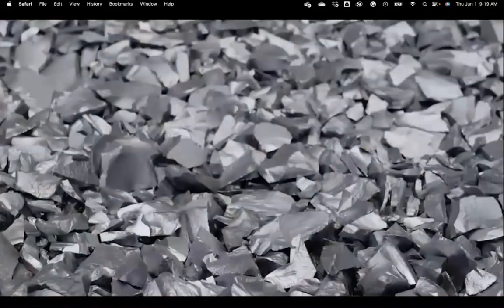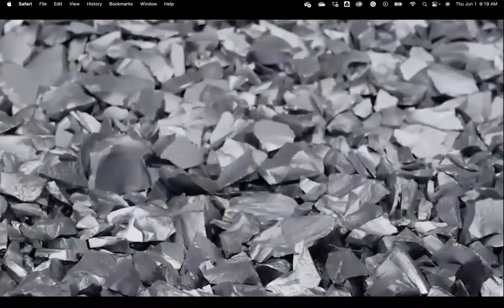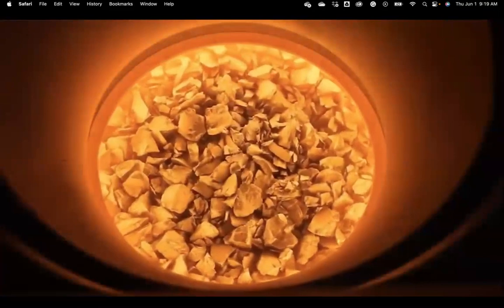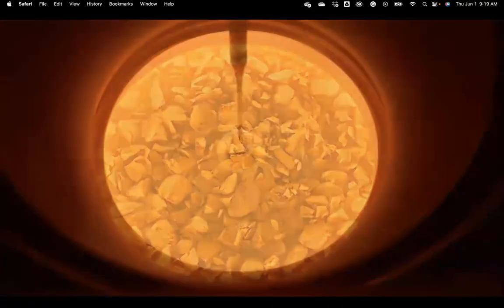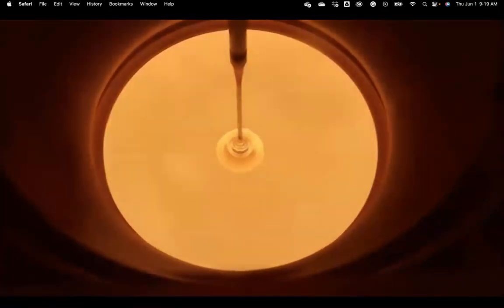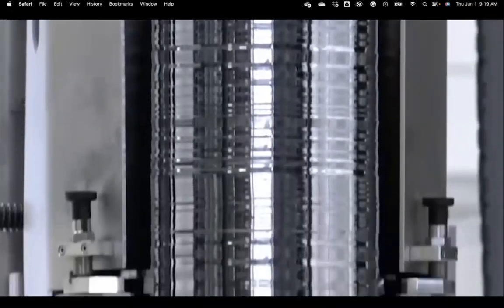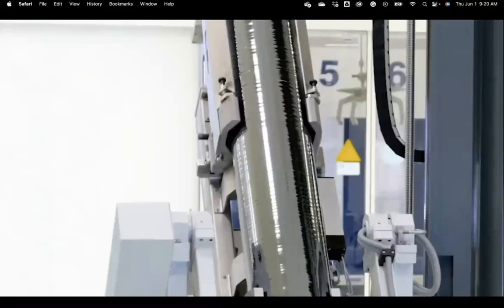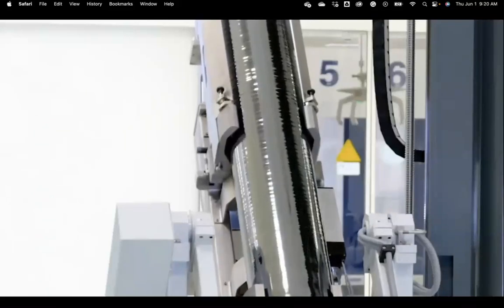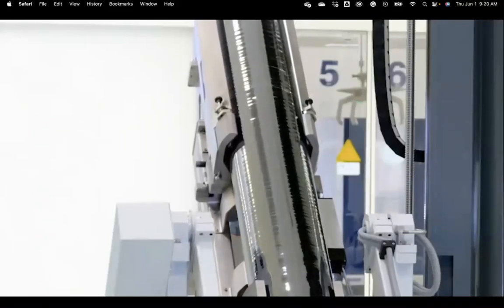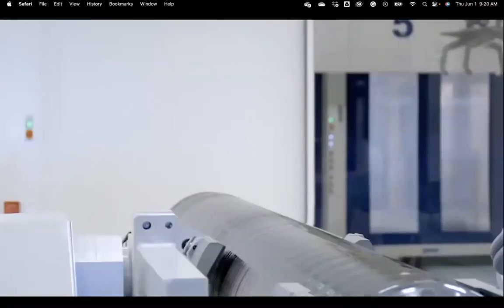To convert silica sand to silicon, the sand is combined with carbon and heated to an extremely high temperature to remove the oxygen. A number of other steps are required to create the finished product, namely an extremely pure monocrystalline silicon ingot called a boule, with only one impurity atom for every 10 million silicon atoms.